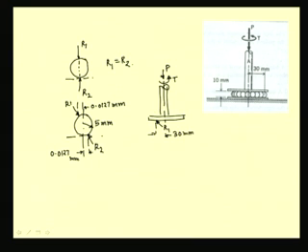So this is a limited equivalent diagram, because all the forces R1 of the various balls have the same direction cosine with respect to the vertical. So from this free body diagram we can write the equations. We have sin theta as the rolling resistance divided by the radius of the balls, from which we can find theta as 0.1455 degrees.